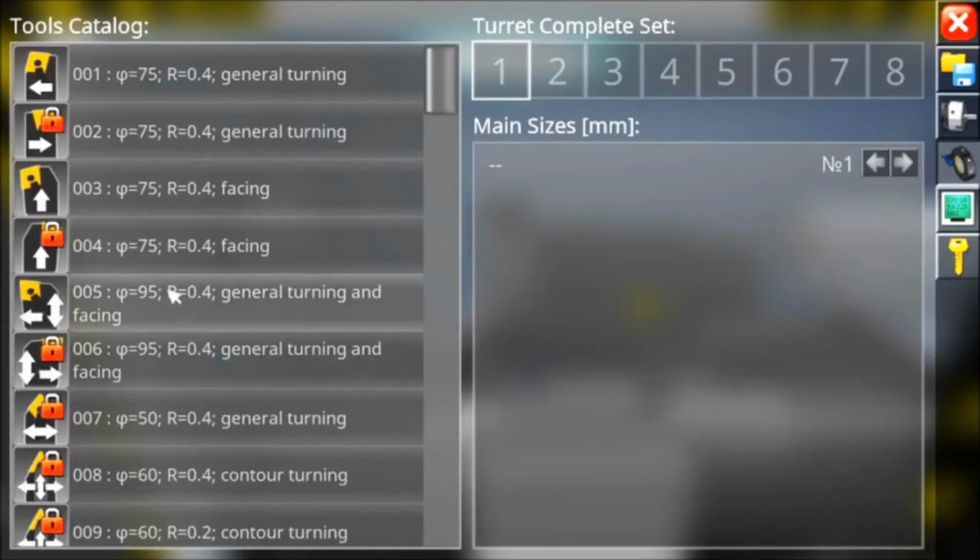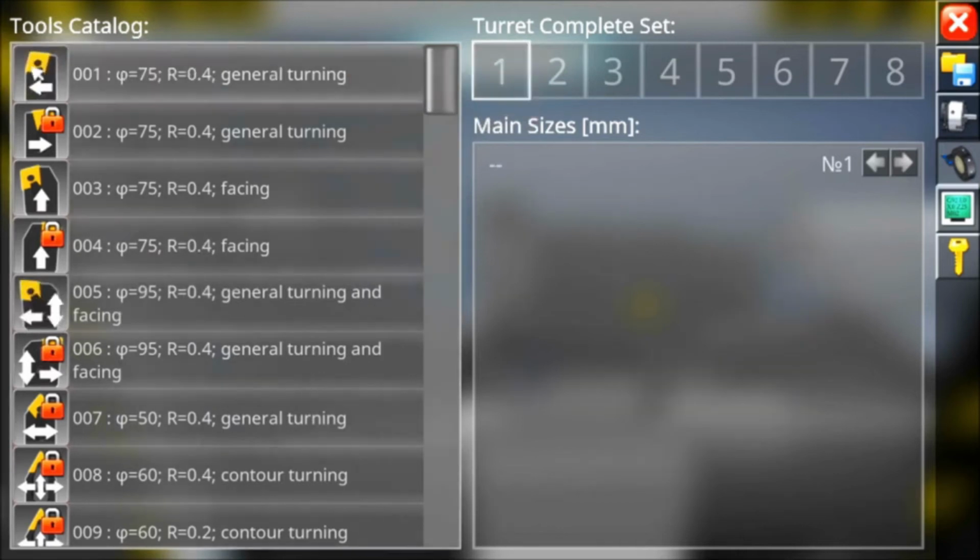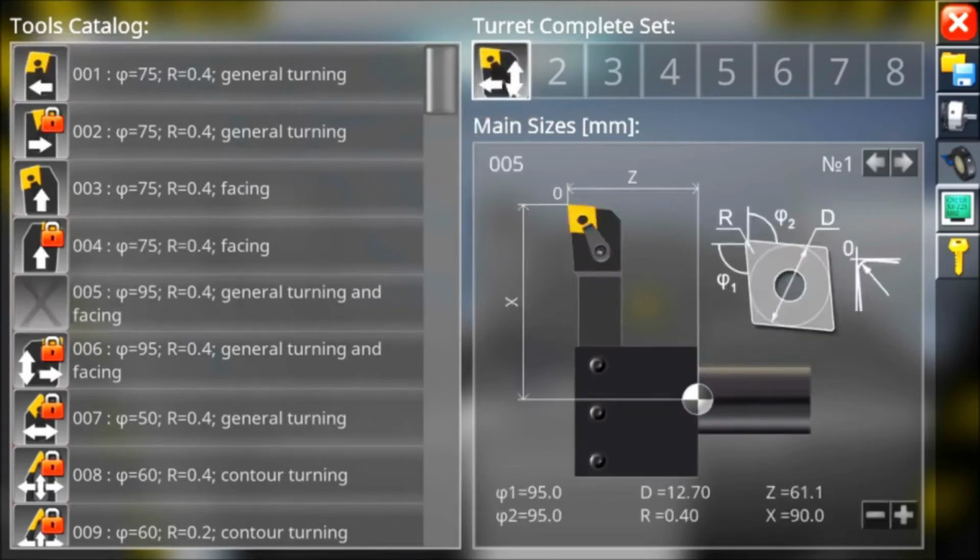In this case I want to turn cylindrical. I'll never go and mount such a tool, why? Because I will be able to turn cylindrical, but not face, so I'm going to mount a tool that allows me to work in both directions. In this case I'm going to choose a CNMG, i.e. a rhombic 80 degrees, radius of tip 0.4 and a 12 mm diameter.